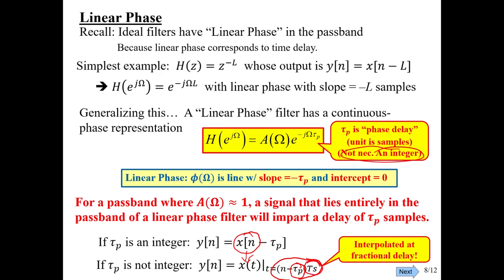So we are reinterpolating the original signal at a fractional delay. Well, there could be an integer part in front, so that tau sub p could be like 3.4 samples. That's how we think about that. And this will play a key role later when we're trying to make things like flangers and choruses. Those are audio effects that we'll be talking about.